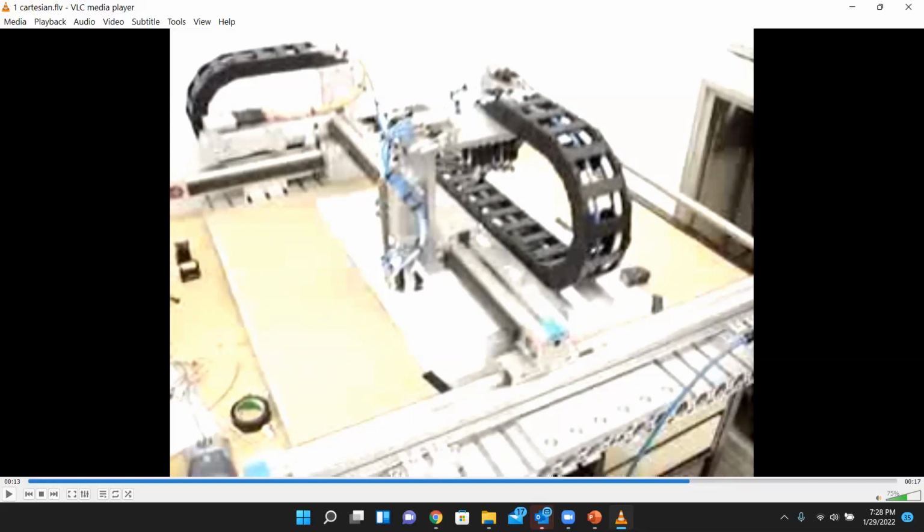So XYZ is basically position. And then you add another motor here, a servo motor, to turn the end effector by a certain number of degrees. And that is your fourth joint. Okay, fourth joint. So it becomes a 4 degree of freedom manipulator. And after that, the gripper, we don't call it another degree of freedom. It is just gripping, right? It's just the tool.